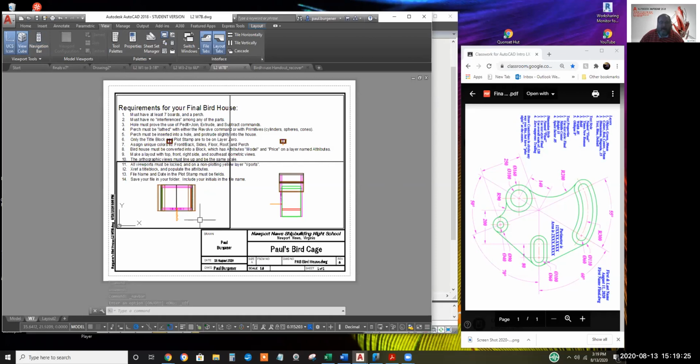You know, always something, ain't it? All right, I'll do it the manual way. UCS, enter. Let's see, I'm looking at the XY plane, so I want to create a UCS that's negative 90 degrees from the x-axis. So click on X option, type negative 90, and nothing happened. All right, I'll type plan.